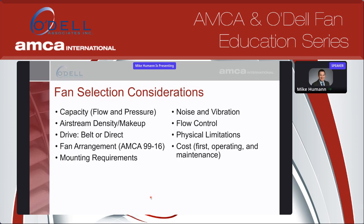You also have noise and vibration concerns. If there's a specification for that, it's certainly something you'd want to know ahead of time to provide the best fan, because some fans are just inherently louder than others. So that's something we definitely want to know up front. Also, how you're going to control the flow of your fan. Is it going to be VFD controlled? Are you going to control it via dampers?